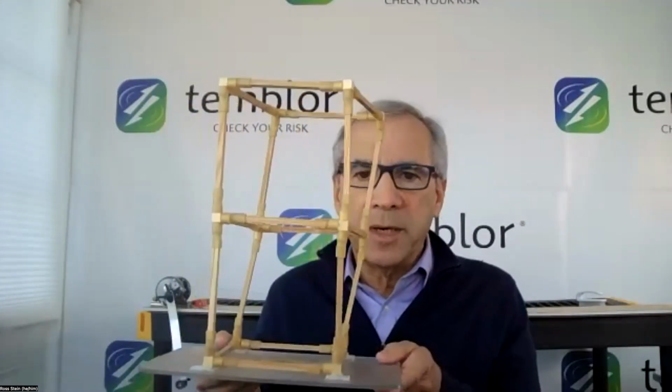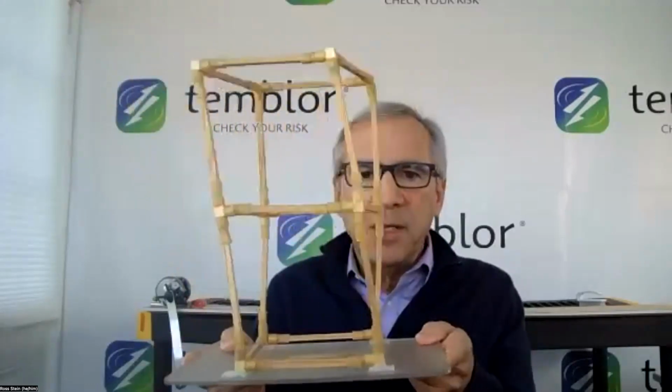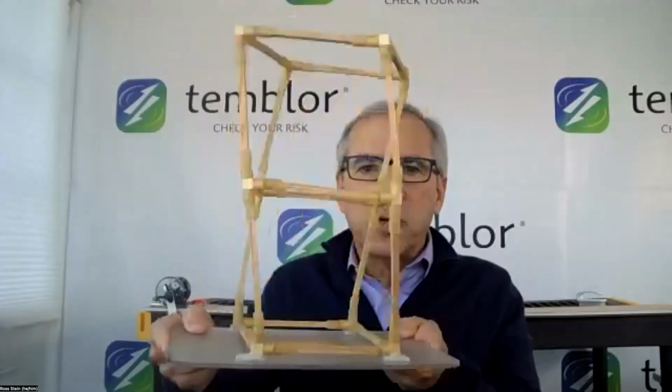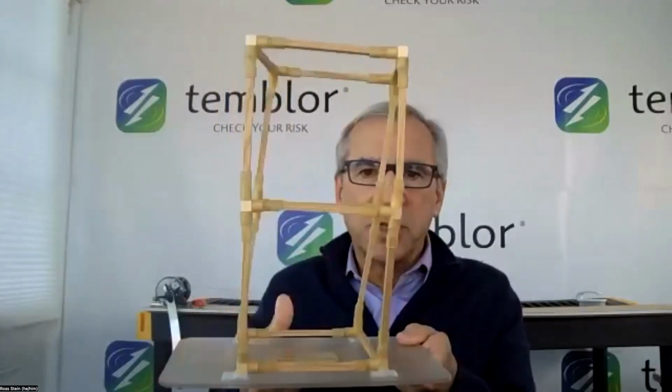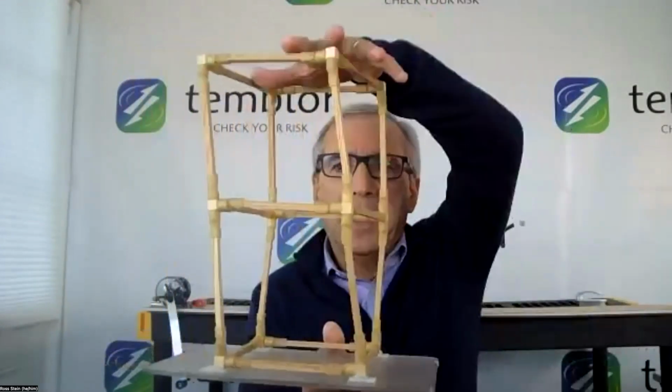Now, what does an earthquake do? Principally, it moves the ground from side to side. And if these corners are weak, the building is going to deflect enormously. Earthquakes also produce torsion. And you can see again that this building is very, very weak in torsion. And if any one of these corners breaks, this building is coming down. And if you don't believe me that a cube has no structural integrity, look at this.